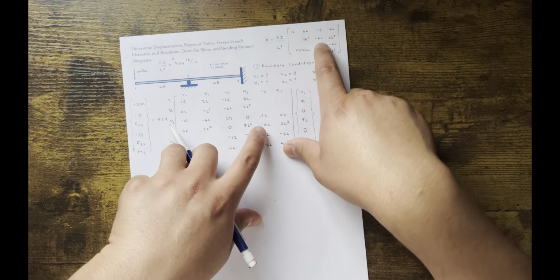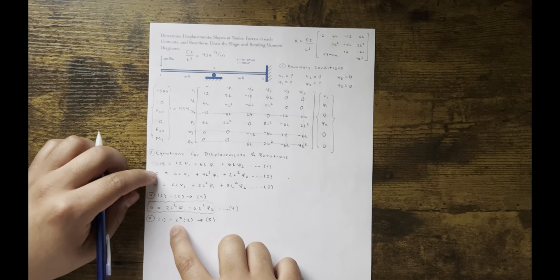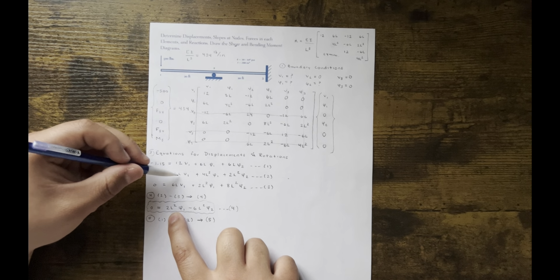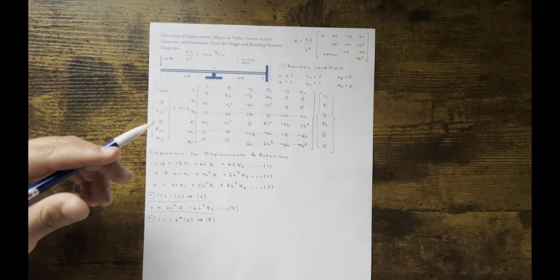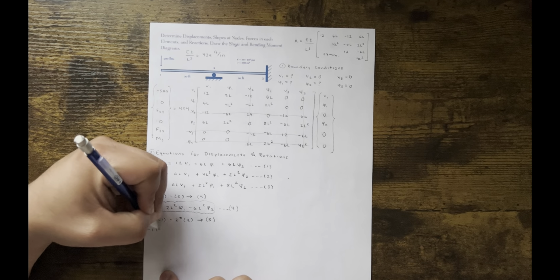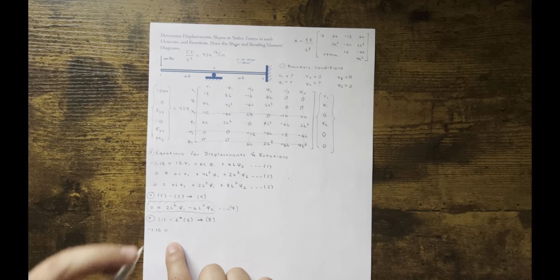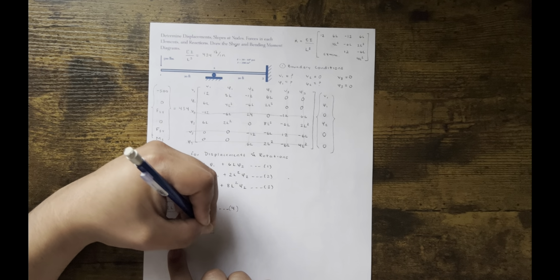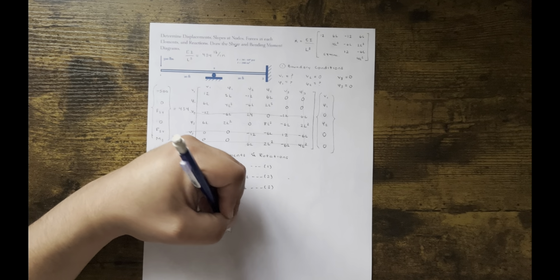Step 5. Let's go ahead and do equation 1 minus 2 times equation 2, which will give us equation 5. All I'm doing is taking this equation minus 2 times equation 2 to get rid of the v1s again. If we got rid of the v1s in step 4, it's good to get rid of the v1s in the other one, or else you're just going to keep going in a loop. When you do that, you will get minus 1.15 is equal to minus 2L phi1 plus 2L phi2, and that's your equation 5.